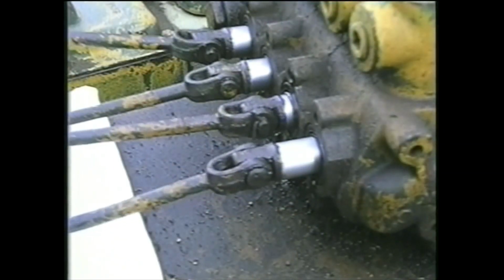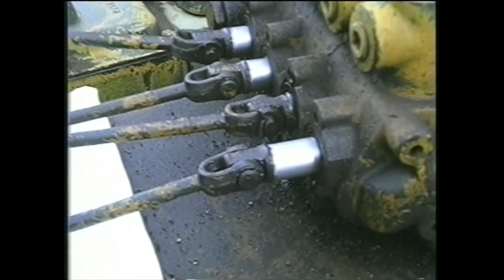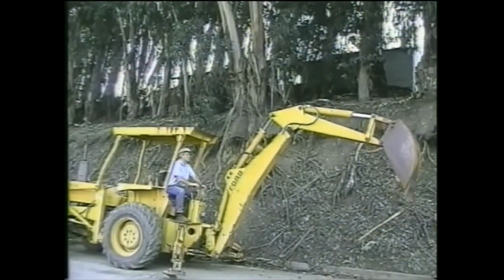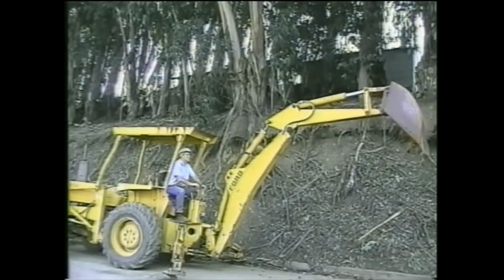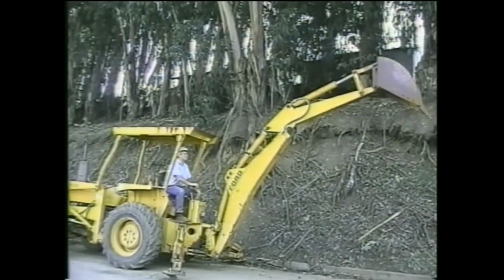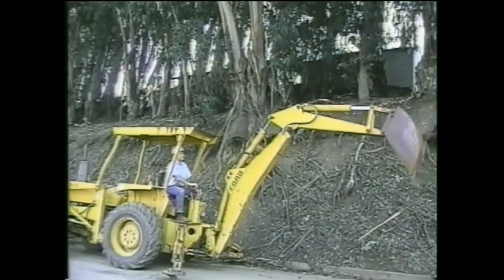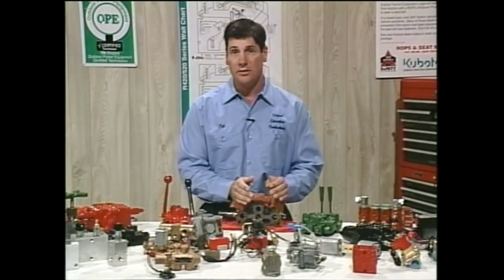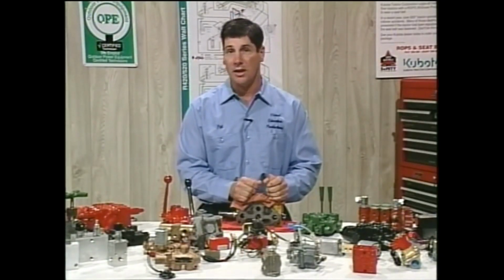External leaking caused by internal abrasion may not appear until extensive damage has occurred. Valve leaks from internal abrasion are a common cause of slow operating cylinders. Slow cycle time on machinery is the biggest complaint from operators. Each of these items, or any combination of these, could be the cause of a slow cycle time.